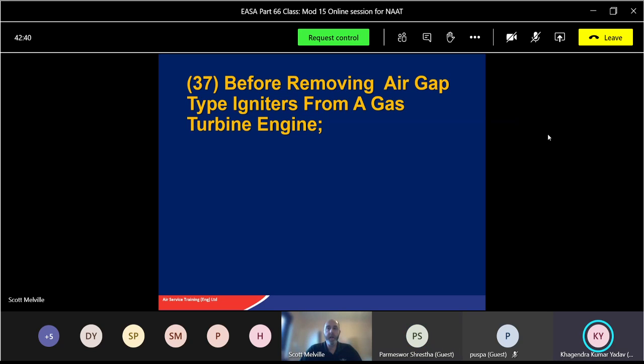Yeah, electrical power first. So circuit breaker. You might gag that, you might put a label on it saying no power to be applied, that sort of thing. Then what would you disconnect after that? The igniter plug? Yes. You're dead.